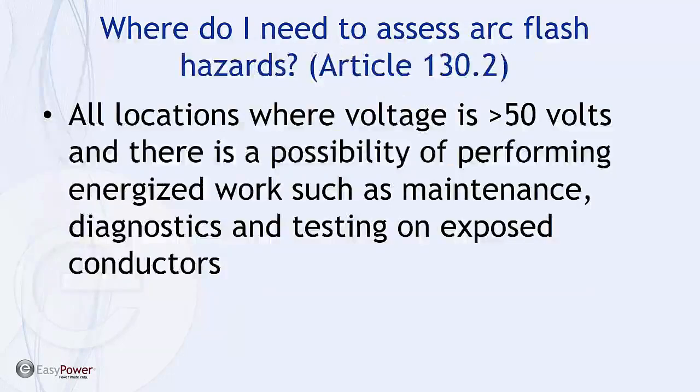So where do I need to assess arc flash hazards? According to Article 130.2, all locations where voltage is greater than 50 volts and there is a possibility of performing energized work such as maintenance, diagnostics, and testing on exposed conductors.